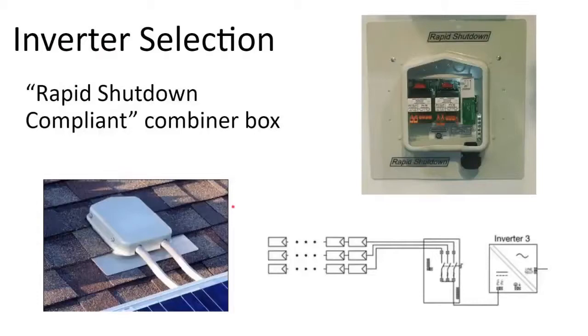Where some of these line diagram creation tools fall short is the balance of system material, wanting you to detail exactly what it's going to be out in the field in construction. So for instance, here's a popular rooftop transition box that's for transitioning the cable to go down into the attic, and being able to interrupt these home runs and say, no, no, no, right here, I want a junction box to transition into the interior of the attic. Sometimes that level of detail needs to be kind of re-highlighted in CAD.